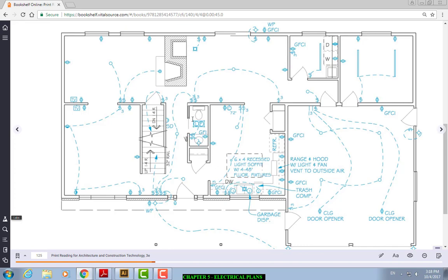You have a restroom or a powder room. You have a switch to turn on the vanity, another switch to turn on the light and the fan. See, L F? And they're together in one switch. So here you have two switches. Here you have GFI, like we mentioned before. Again, three-way switch here for that light. Switch here for that one. Outlets. Switch here to turn on the light outside. You have an outlet outside, waterproof GFI, light fixture. An outlet right there, and the kitchen.